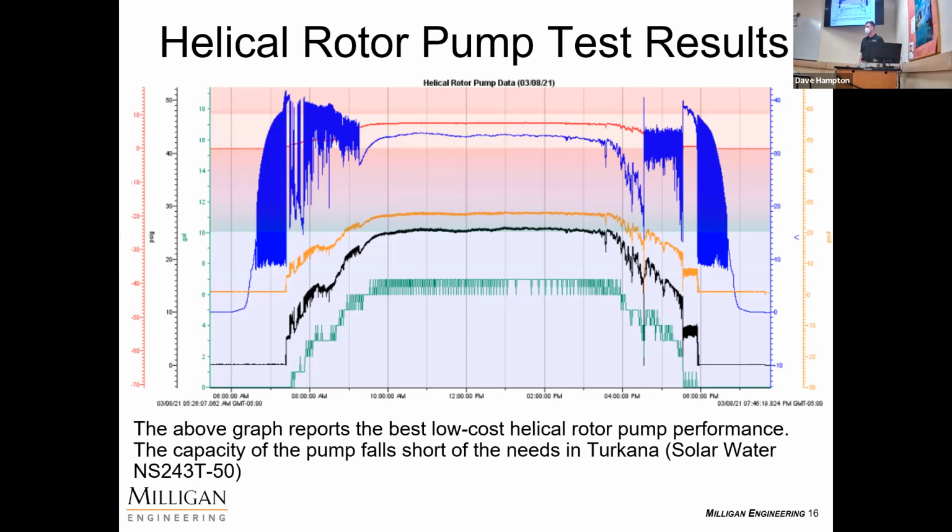Were they willing to share the theoretical basis for that with you? That would be something we have to go back and ask. So you might expect a question next week, same question. But that would be good to know as engineers, what is the theoretical basis behind that claim? Could it be that as the voltage drops, the current increases? Yeah, we're thinking there's a high current at sunrise and sunset conditions when the pump doesn't really have enough power to pump any water. It's just sitting there. It's sort of a high current condition.